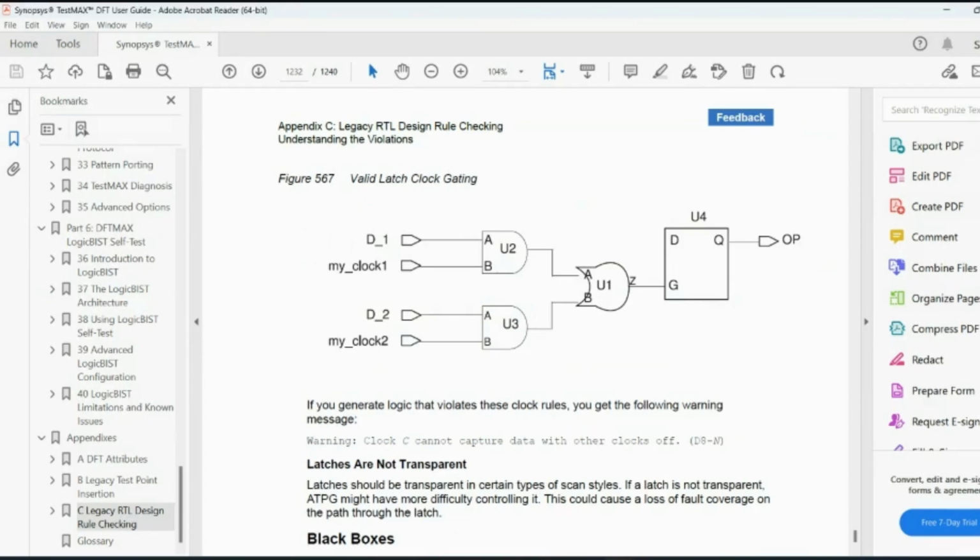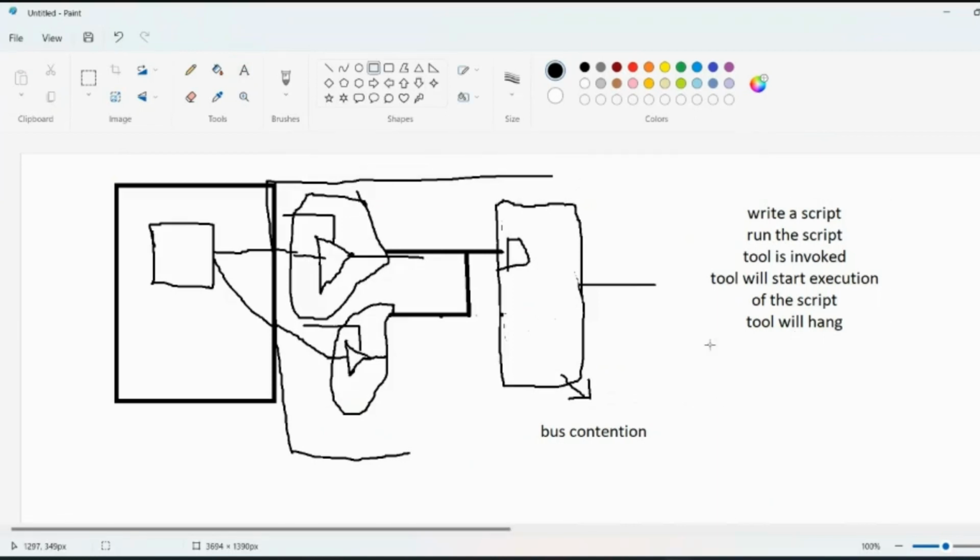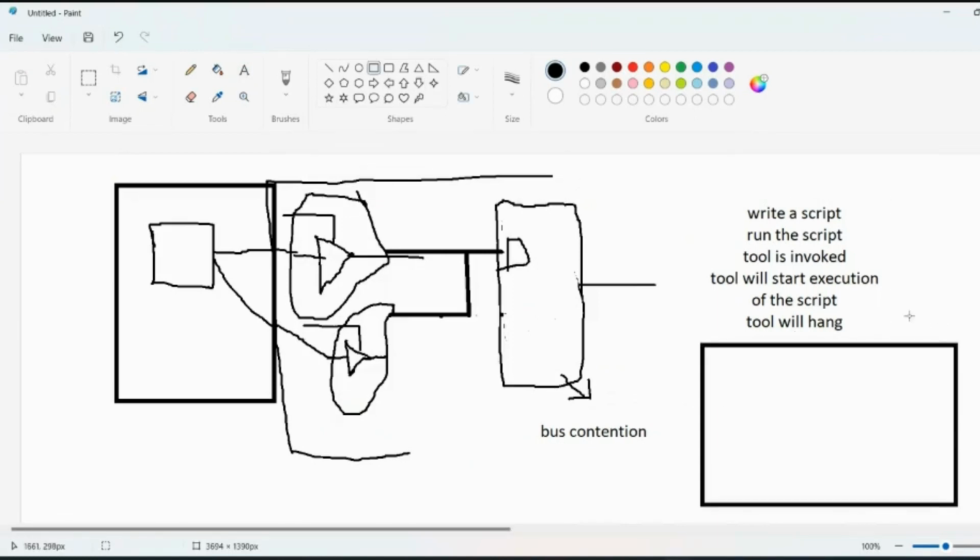As last time I told you guys, we read in standard cells, right? So your entire SOC design will be using the same kind of standard cells. Standard cells means the standard cell libraries of AND gate, OR gate, NOR gate, clock gating cells, flip flops, registers, muxes. All these are individual modules or elements that we have. For all of that, we will read a common style. So the RTL design engineer also has to use the same standard cells. Whatever the RTL design engineer uses, we use the same.